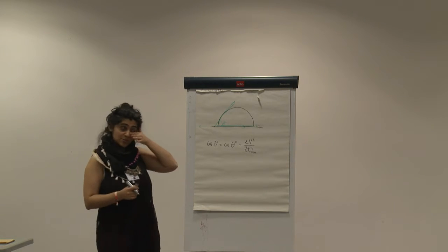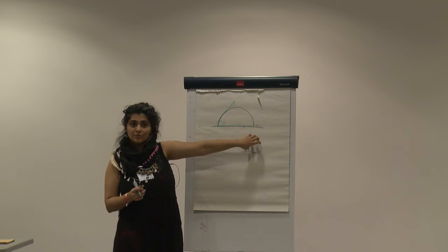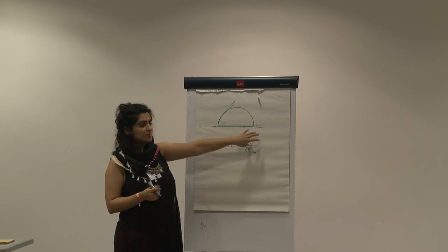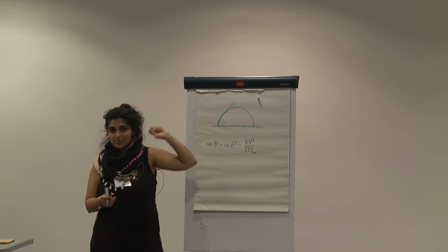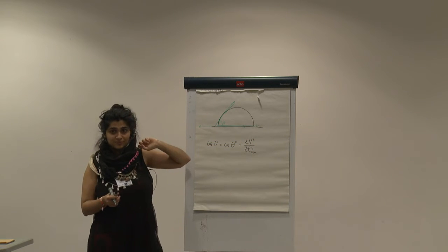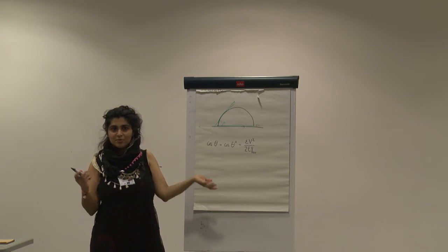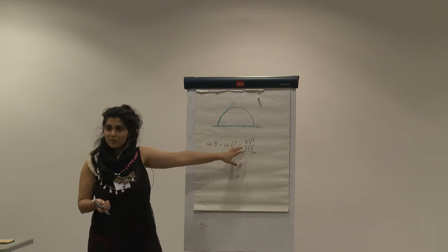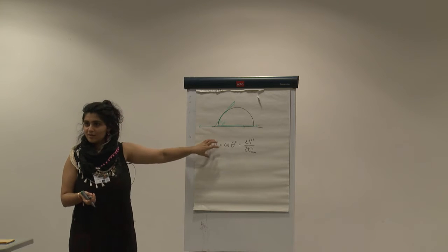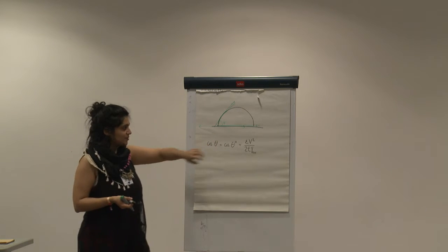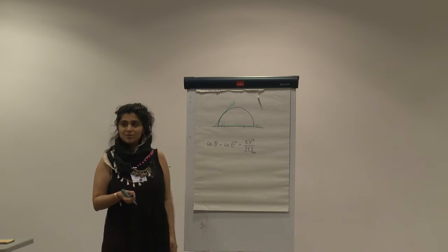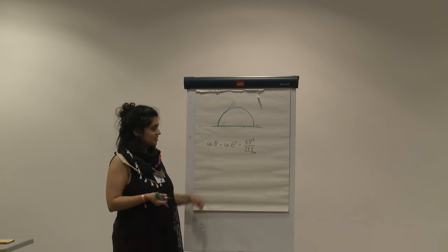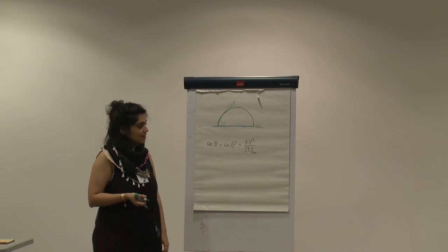Now back to your question. We can have very high voltage here. I know people that have been trying, and you can see them on YouTube, to move droplets with 700 volts or even more. I'm not joking. People want to see the droplet moving. They know the principle, and if you're desperate, you want to get this angle as sharp as possible, so you increase the voltage. And you can see that the voltage is the most effective way to do that, right? It squares, and then you have a higher angle.